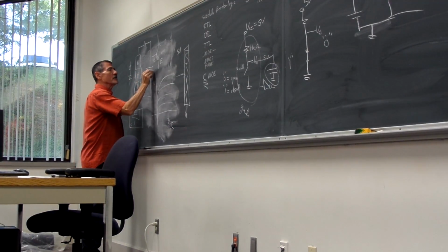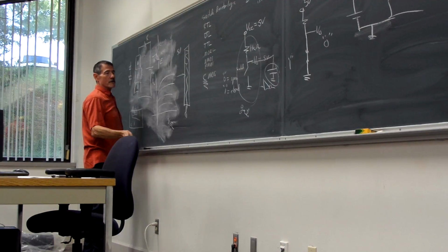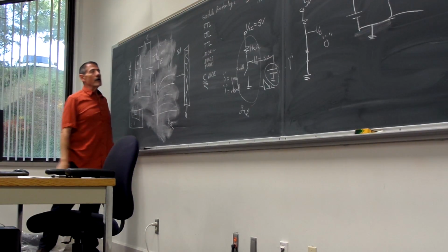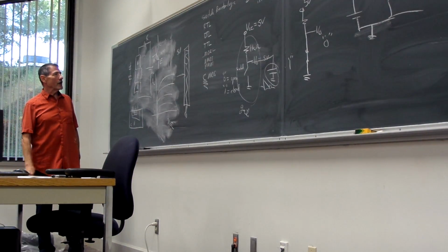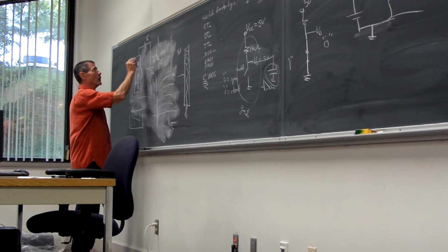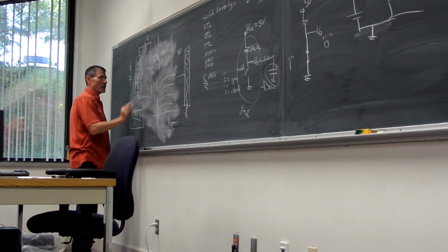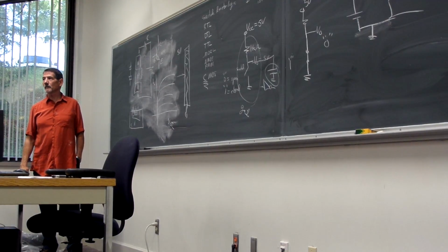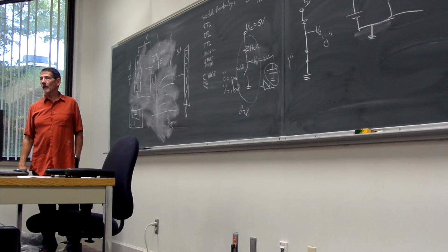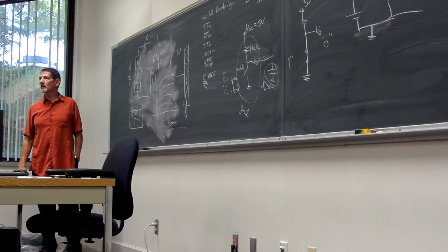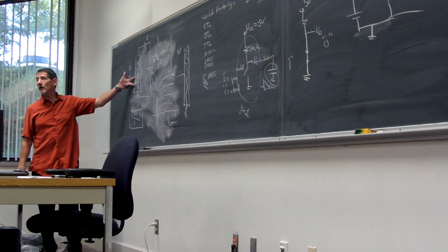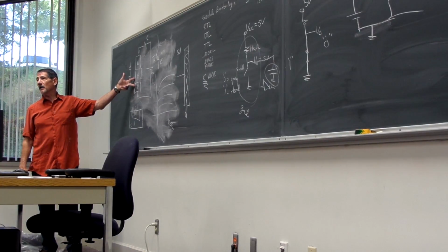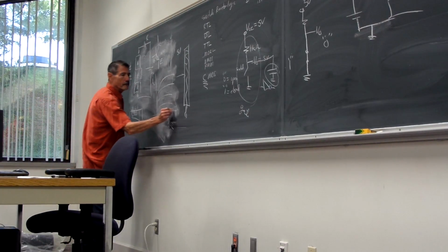This is VCC here. This is a resistor. What if there's absolutely no current going in? What's the voltage from the collector to the emitter? Okay, no current going in. Anything exciting going on here? So we can model it as what? Open circuit. So it'll be VCC.